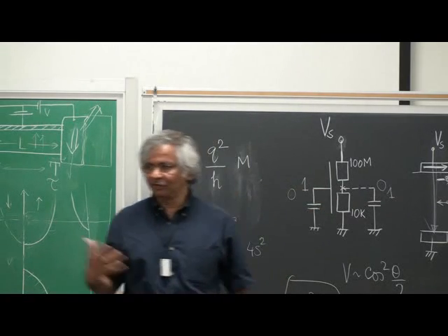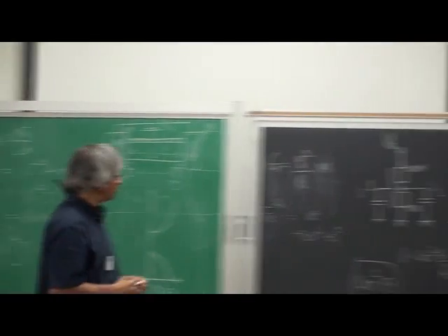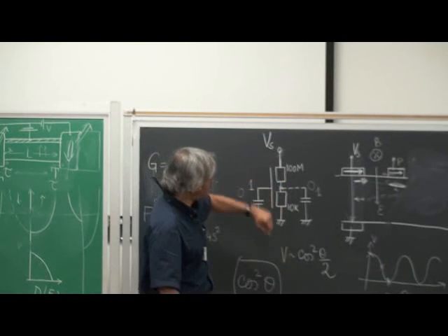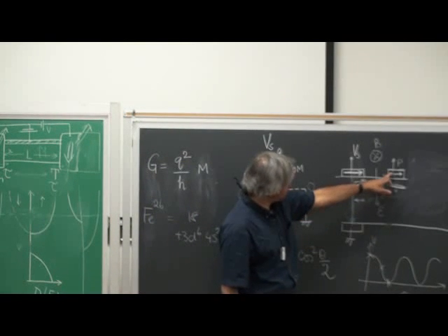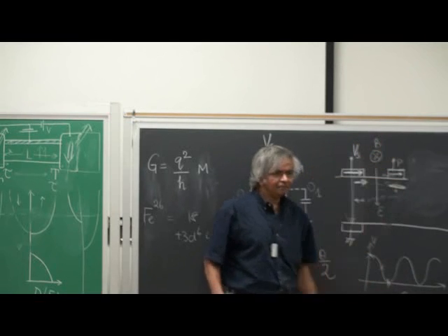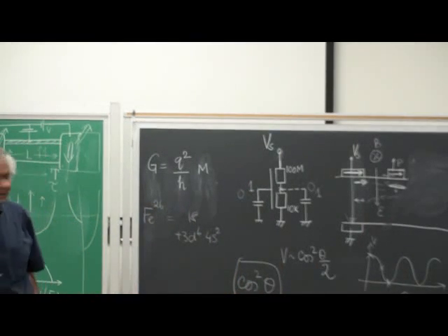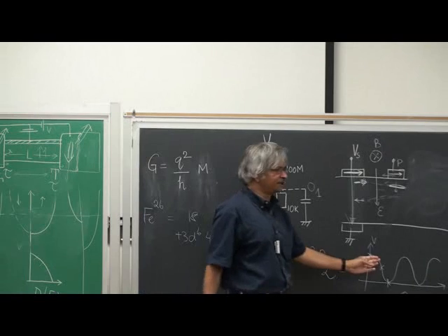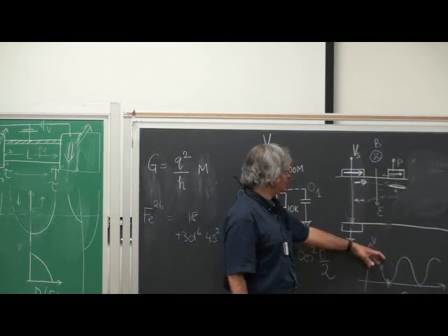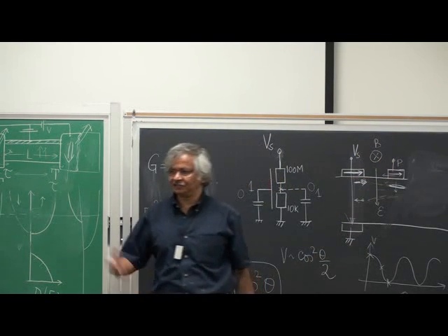And when people talk about, well, how do I use spin? The thinking usually is that somehow using spin, you have to figure out how to change the resistances. And so from that point of view, the way you think is, well, I can change that voltage out there by changing the field here, for example. But when you think that way, you don't see any real advantage relative to CMOS. Because the voltages that one measures experimentally are typically tens of microvolts. And then how do you, again, turn it into a gate voltage that you can actually use to drive the next stage? That's not at all clear.